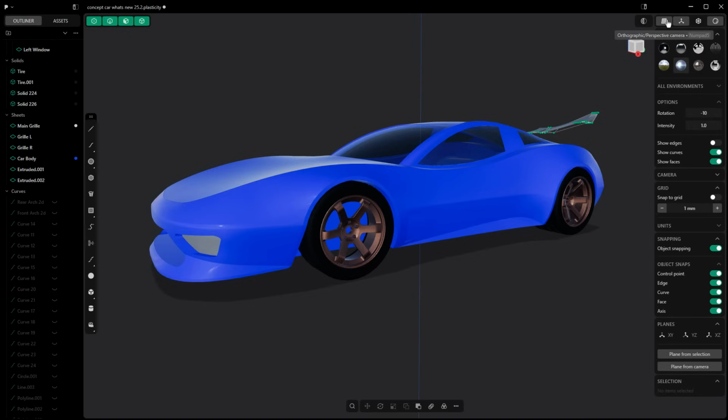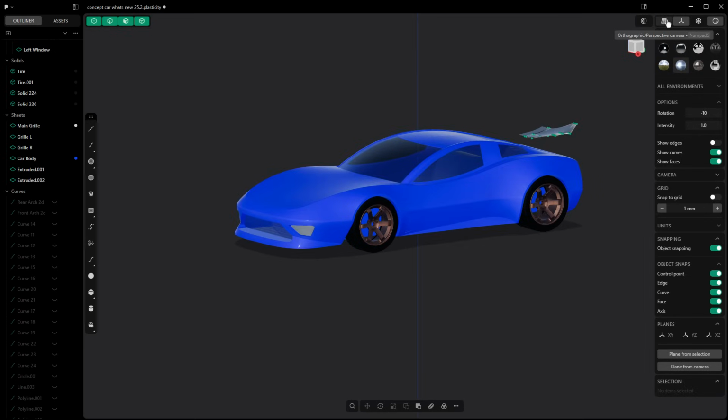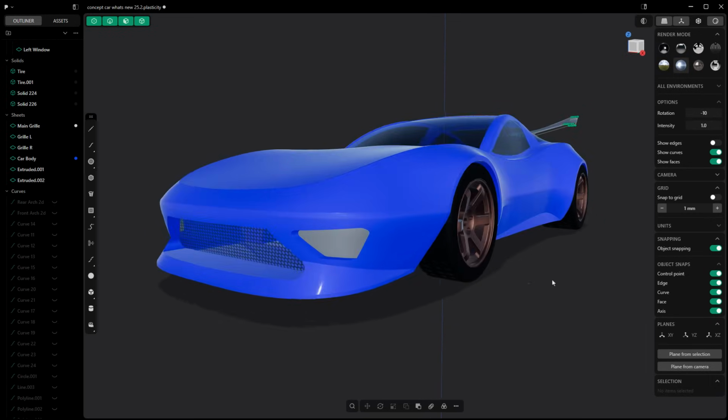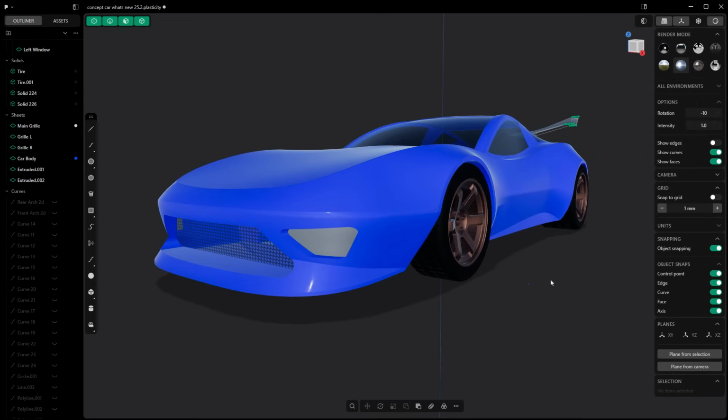And so with the perspective camera, the perspective has changed. It used to be set at 50 and now it's at 35. And that is an option that you can change if you notice any clipping on your model. So something that used to happen, especially with really large or really small models, is you may get a lot of clipping, and you can go in and manually adjust that value to make it lower if you find that you're still getting clipping on your models.